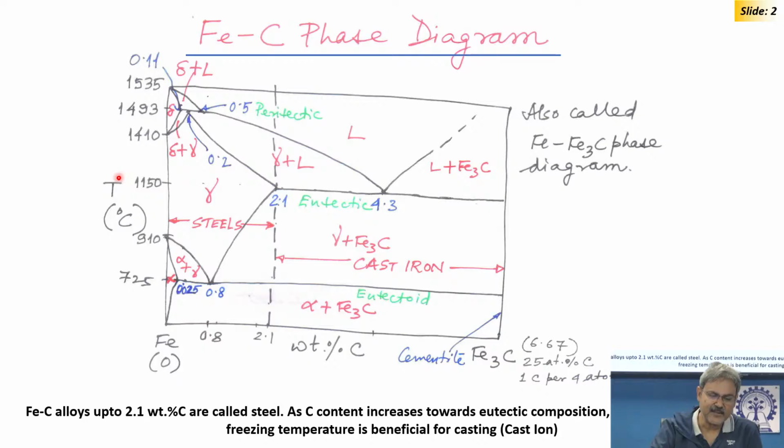This is the iron-carbon phase diagram, you all know. These are the background slides. There is a high-temperature delta ferrite transformation, which is of immense importance. Then in the steel part there is up to around 2% carbon. Then we have austenite, which is FCC, which eventually transforms into BCC ferrite. Whether BCC ferrite forms first or orthorhombic cementite forms first depends on the carbon content or carbon equivalent. If it is a low carbon steel, then pro-eutectoid ferrite forms, and there is a eutectoid reaction.